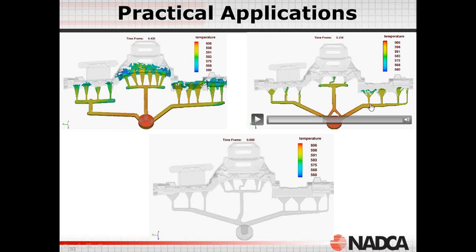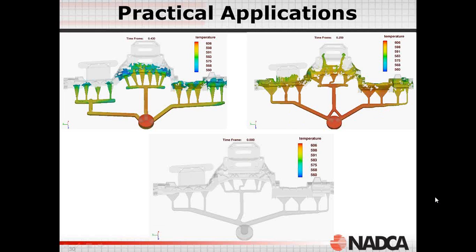One thing we saw here was that this branch scoops material into itself very quickly, and one way of changing that is to just change the radius of this corner. And we can see an improvement in the simulation. So it's actually heat loss during pre-fill and filling that is the reason why we need to get the timing of all the gates to be as balanced as possible.